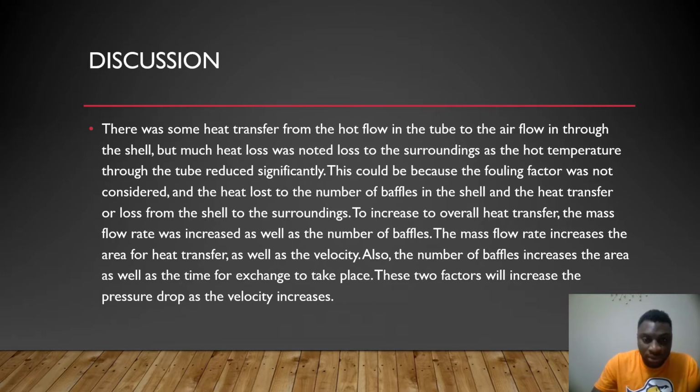So this also increases the heat transfer, and reducing the velocity will increase the heat transfer. Also, the number of baffles increases the area, so there's more surface area for the heat exchange to take place. These factors could increase the pressure drop as velocity increases. Those are the things I noted during the calculation that could help increase the overall heat transfer.